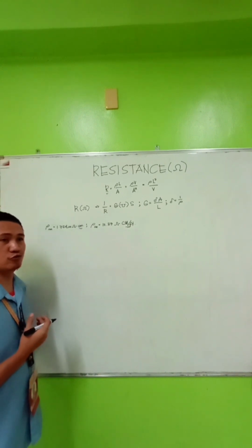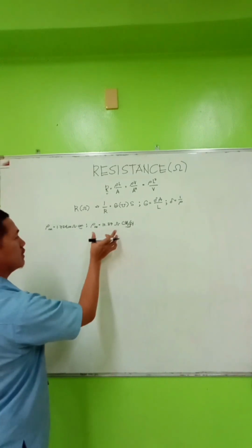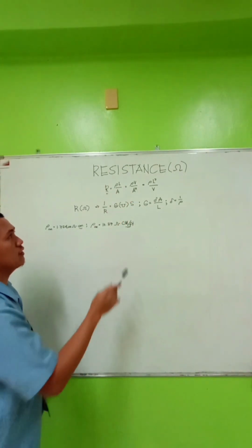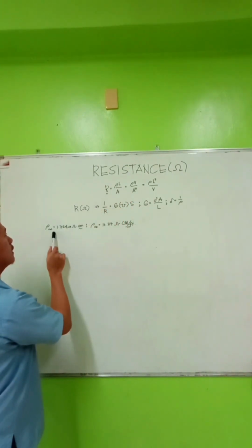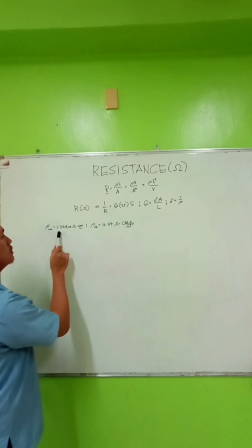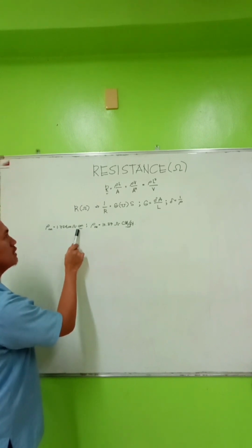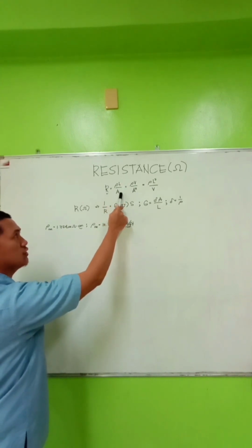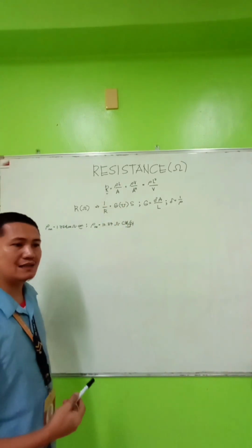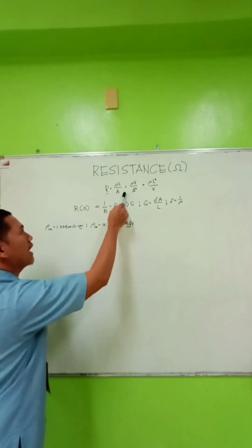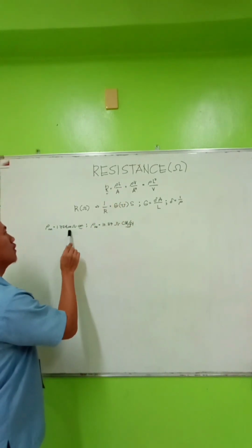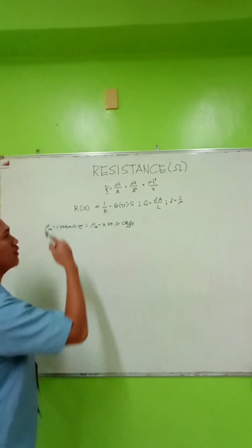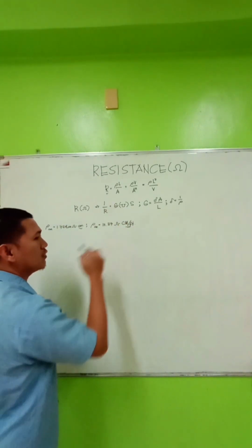factor follows. Okay? So it means that the reference, for example, if the resistivity given is 1.724 micro ohm centimeter and your length and the details of your cross-sectional area are in different units, you need to convert and align to your resistivity, which is your centimeter unit, or the other way around, in circular mil or in feet.